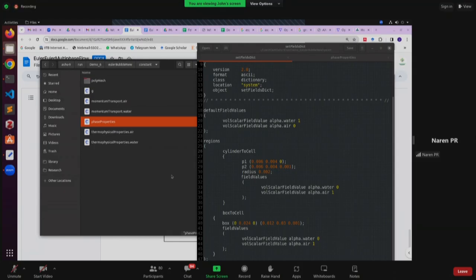Typically in a bubble column contactor, a gas is passed into a liquid. The gas velocity would be of the order of only a few centimeters per second. It could be just 10 or 20 centimeters per second, and 20 centimeters per second of gas sparged into a liquid is actually a very high velocity for that system. So for all practical purposes, it will remain an incompressible flow system with constant density.